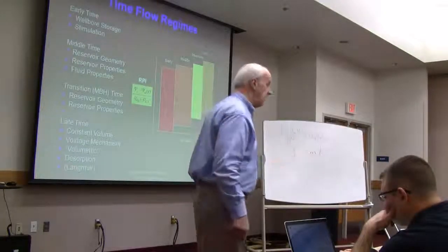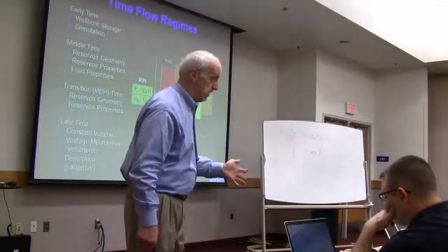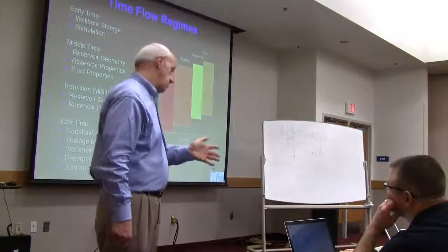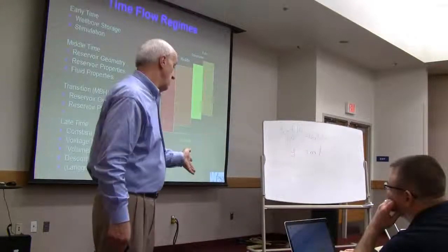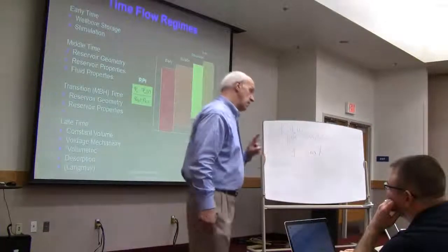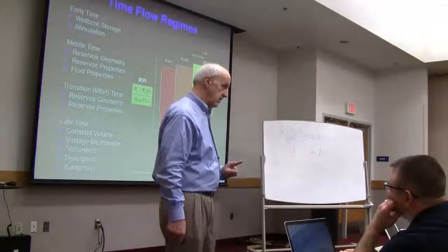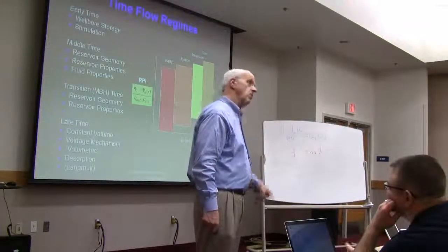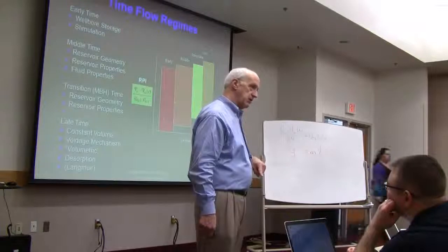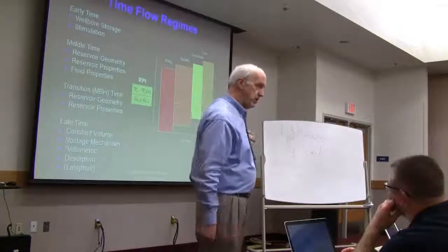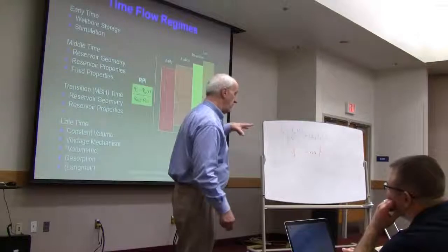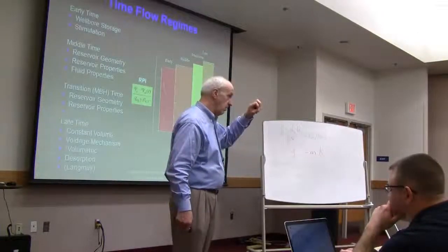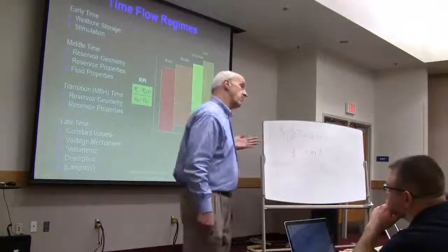If it is there, then it is part of the system behavior, and part of our decision then is how to make use of it. Sometimes we ignore it because it's not important. Sometimes it's everything. And I can tell you with absolute confidence, in the Marcellus, if you do not have a significant natural fracture component to the well's behavior, the well will not be economic. It's that simple. That's a real game changer, because all of a sudden my goal is not necessarily to connect to the reservoir, it's to maintain a connection to the natural fracture system.